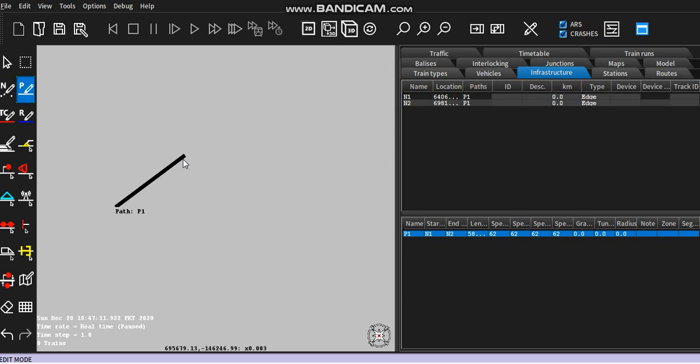You might be aware of the track circuit from my previous lecture. Track circuit is used to identify the train location or position on the network in traditional signaling control system. So once you have developed a path, then you will have to assign a track circuit to that path so that you can understand the position of your train while it is running on that path.